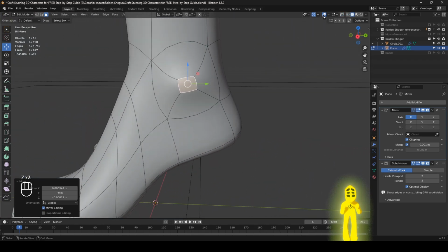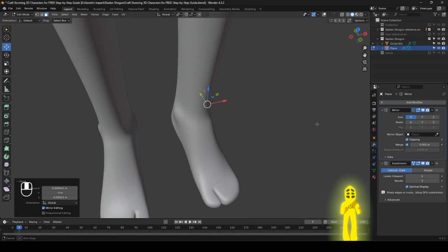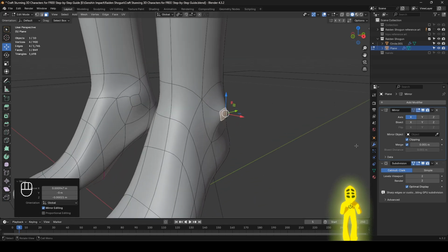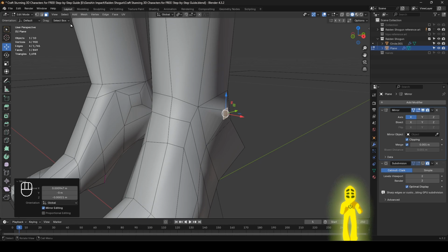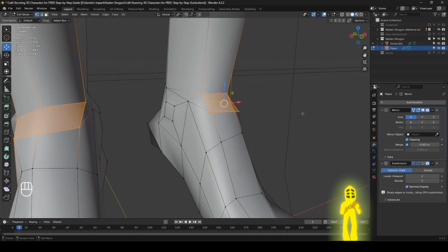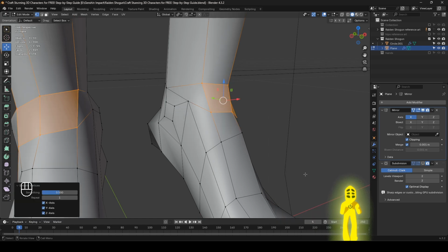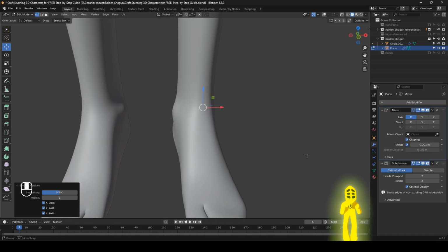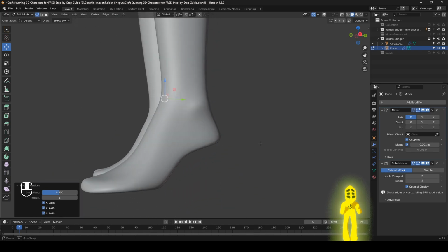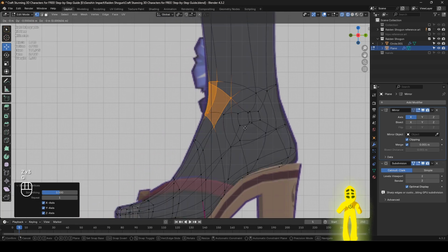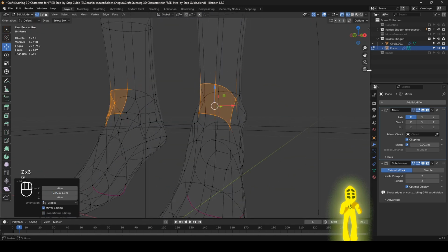All right, turn this off and give it a look over. It doesn't have to be that complicated. I am getting a little bit of weird stretch artifacts right here, so let me right click, smooth vertex. Now when I look at it, it's better. But still make sure it follows your reference. Let's stretch it out a little bit. Corner view.